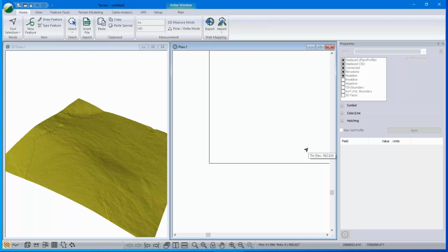If, however, the survey is a meter low at one end and a meter high at the other end, not so easy to make them line up. But it's easy to bring the survey data into a hole in the LiDAR data so that you've got survey in one zone and LiDAR in the other zone. It's not that easy to make sure that the place where they meet is smooth.